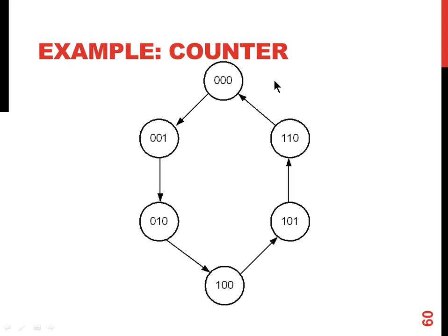Somehow, if the FSM, the machine or the digital circuit goes into one of these two states, we can have a self-correcting FSM where, for some reason, if the digital circuit goes into one of those states, it can come back into the previous known state, not the next state: 0, 1, 0 in this case, and 1, 1, 0 for the 1, 1, 1 state.